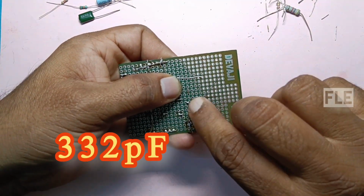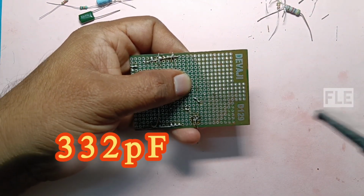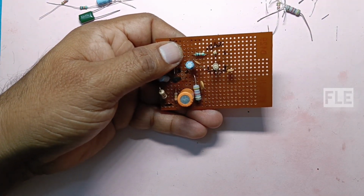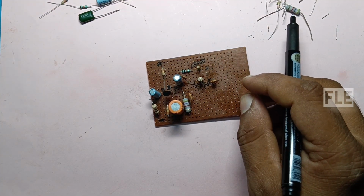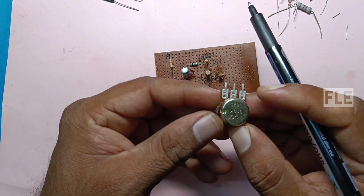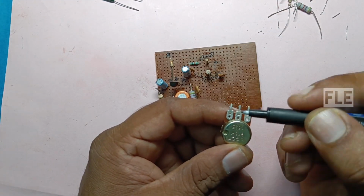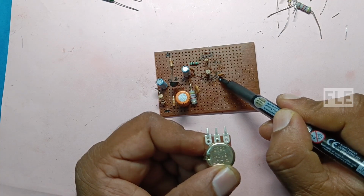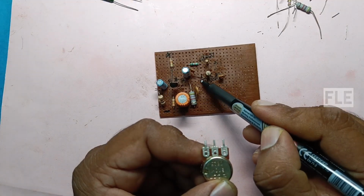A 332 pF capacitor, one terminal is connected to the third terminal of the treble controller. The treble controller has three terminals. The center terminal is connected to the 5.6K, the first terminal is connected to 332 pF, and the third terminal is connected to 332 pF. A 47K potentiometer is used for both the base controller and the treble controller. Three terminals are connected to the three terminals of the potentiometer.